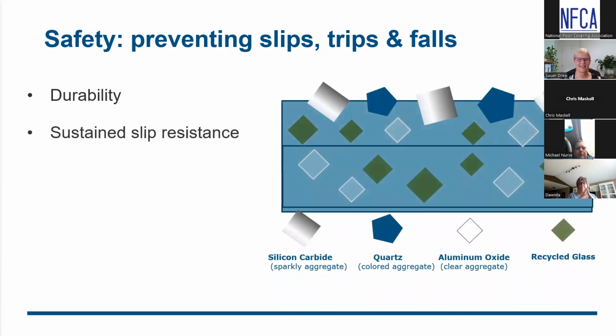Yes, yes. Like how many times do we see a beautiful floor put in and just cut around the drain and siliconed because the wrong drain head was put in? It should be clamped and pinched down so that it's waterproof, grease-proof, cleaning fluid-proof, and lasts the lifetime it's supposed to. The alternative is just awful, and it's an ongoing problem. Every day we run into this. I should put it on every slide, is what you're saying.